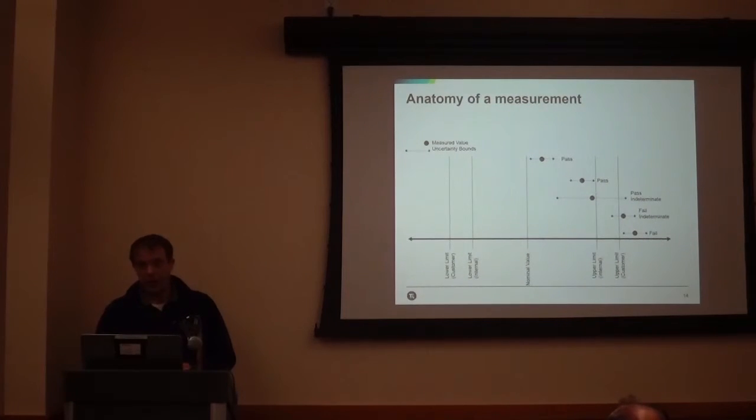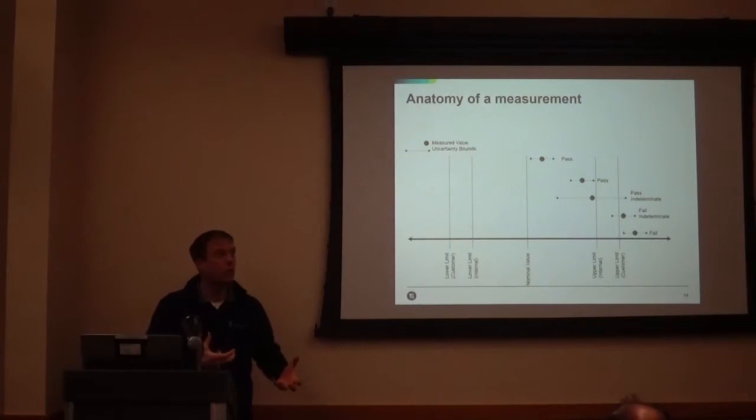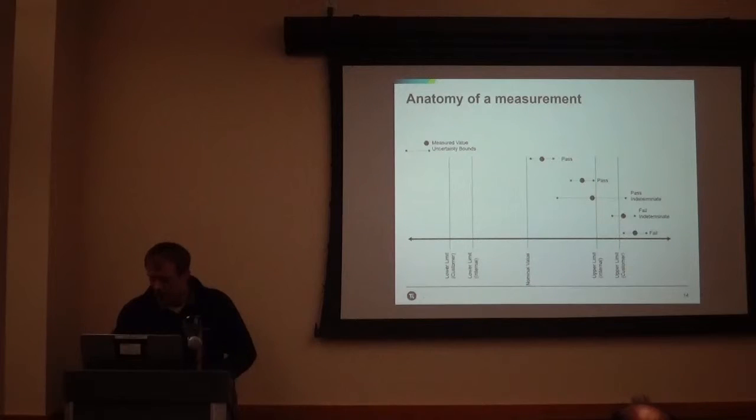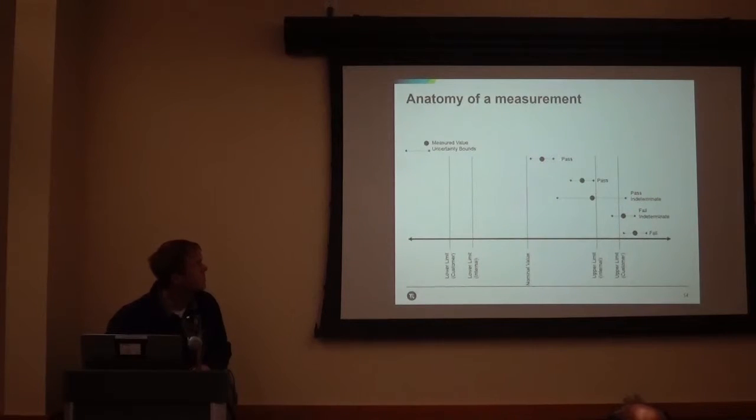TestStand has no idea about any of that. It passed, it failed, it errored, it skipped, it's done. So we have to add that into it, or go really crazy into your metrology standards to the point where you only measure values and report values and do not make any determination of pass or fail to the end customer. That's their responsibility to do, but nobody really wants to listen to that unless you're a metrology lab, and those are not our customers in general.